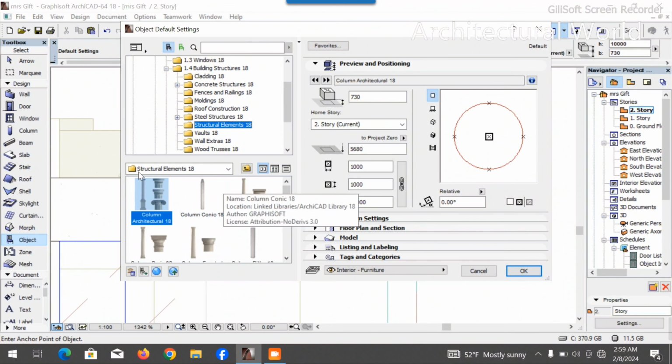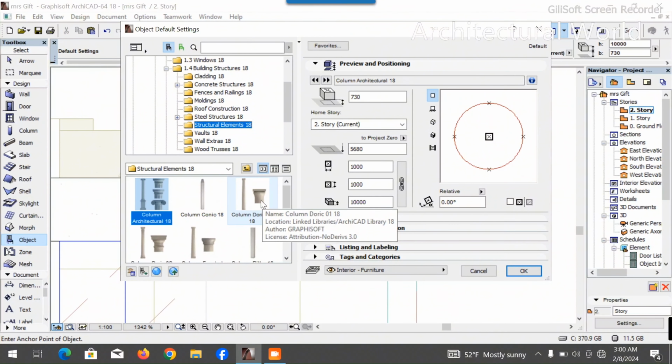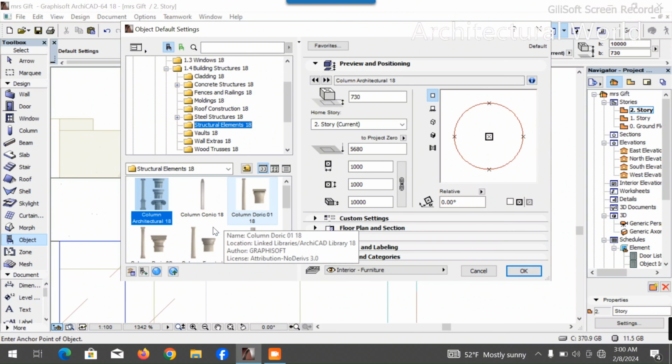So first of all, I think this is more simple than the other one, so let's work with this. Let's take this, which we have already taken, and we have the bottom offset. I want the bottom offset to be 0. Let's start the settings from here. Now this column height is telling me 4950, and I want it in total of, let's say, 3 meter.